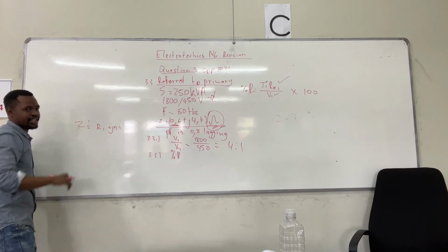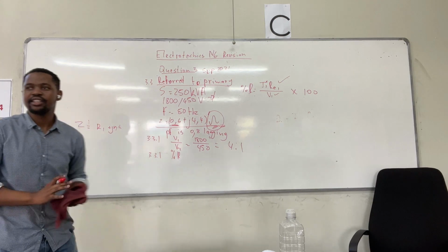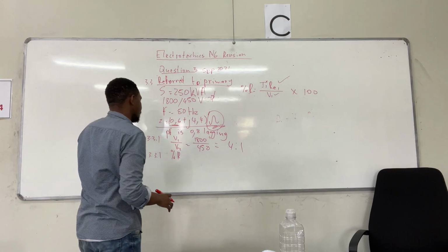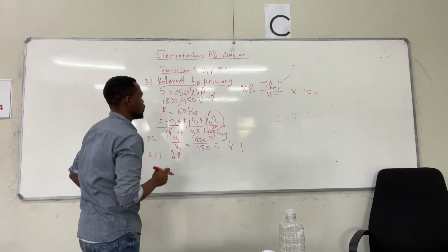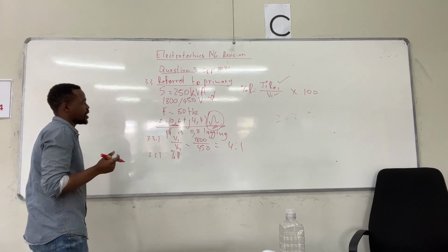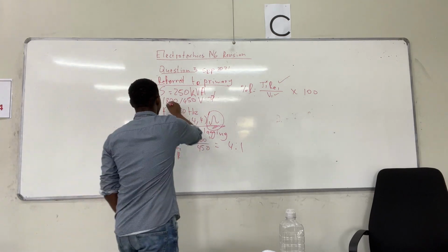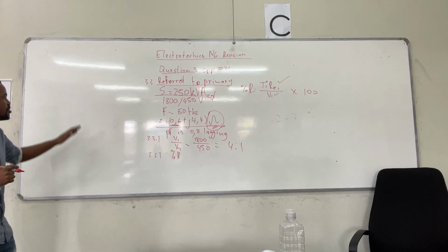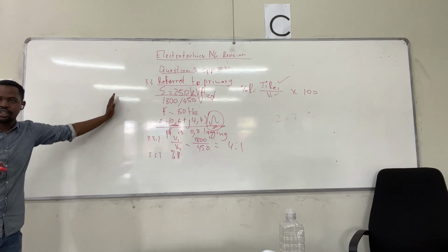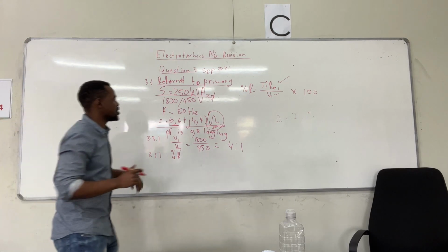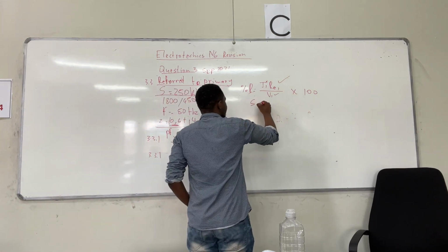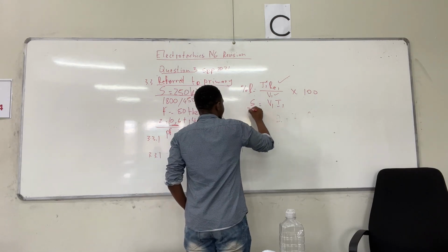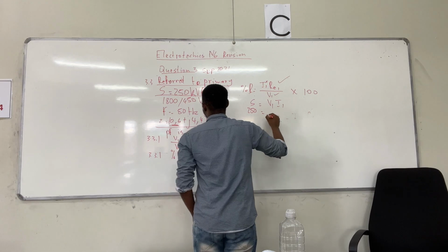That means you have been considered as a secondary circuit. So we're only short of the current, which is easy to calculate. Remember the rating of a transformer: you can use it with the secondary or with the primary. So I'm going to use it with the primary, where S equals V1 I1, which is 250 over V1.